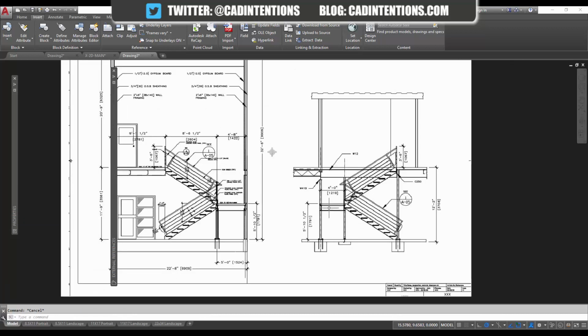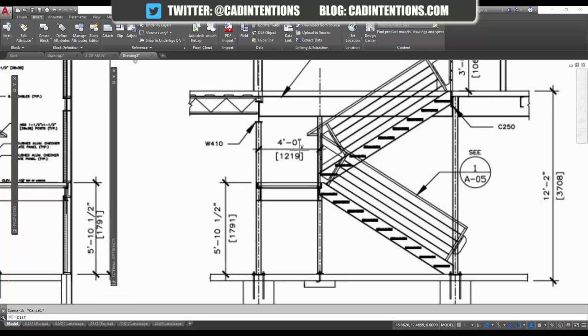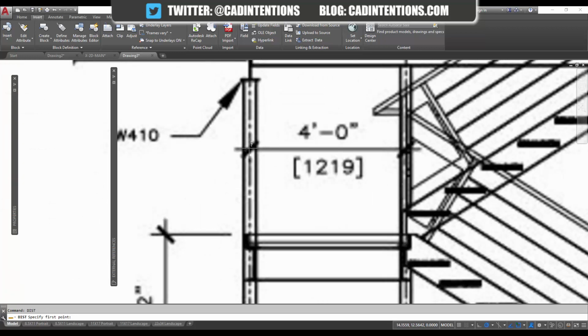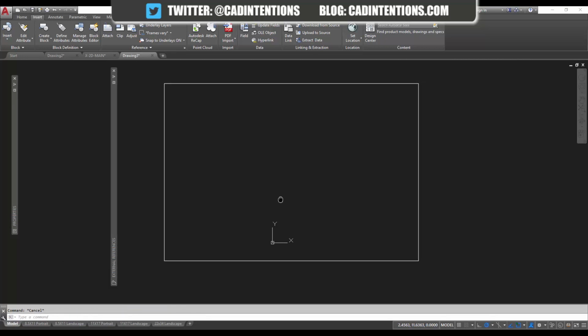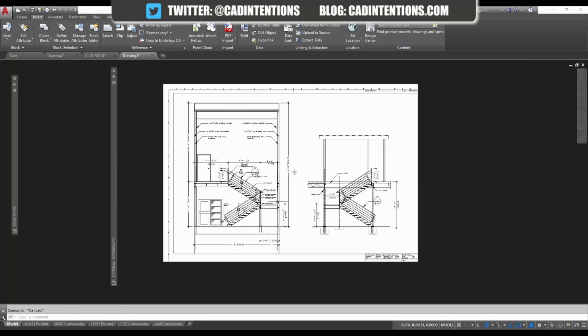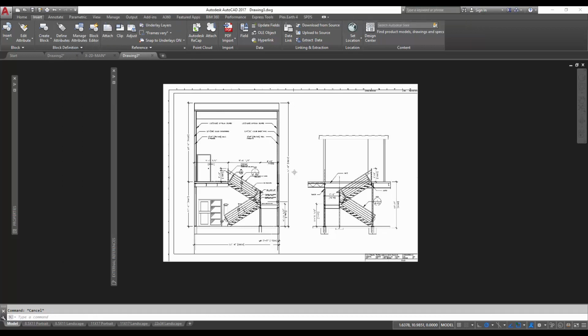So if I had been a little bit more accurate in the lines, we would have been exactly at 32.5. But now you can go and check these other dimensions throughout the drawing, and you're going to see that they're all pretty much close. So we can go from here, this tick mark, to that tick mark, and you can see it's 4.01, should be 4.0. So there you've got a pretty accurate and super quick way to insert and scale an image, and you can use these for reference in your drawings, a background ortho, or simply just to spruce up your drawing as a background image.